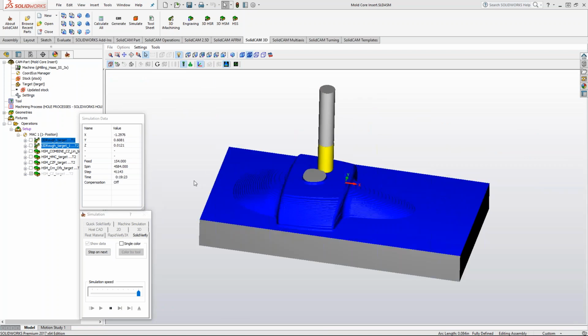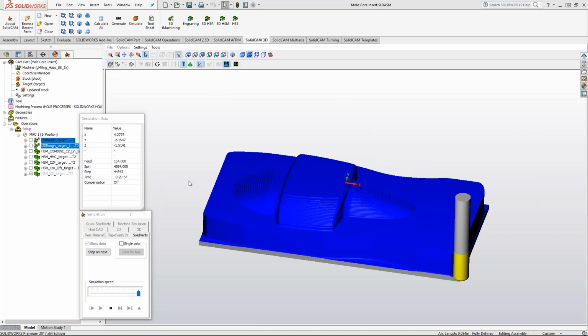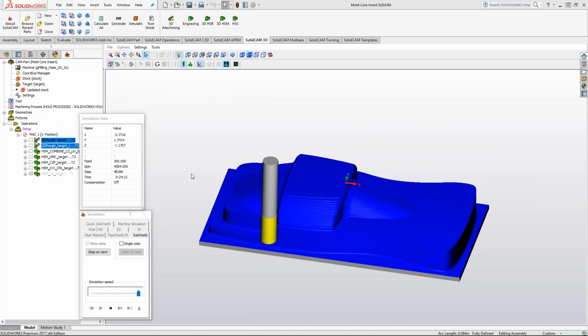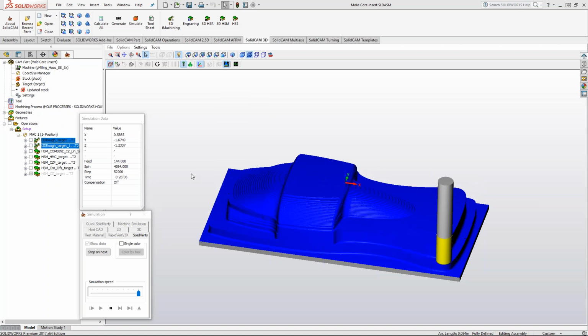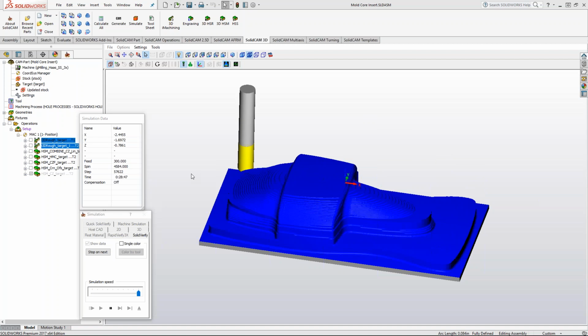I think this part was actually a clear part, so I had to have a much better finish on it. And again, this was P20 material. I think it was 28 to 30 Rockwell C. And that's what I ran most of the stuff that I did out of, was P20. It cuts good. It's pretty consistent as far as the finish goes, and it's easier to polish, and it's real shiny and pretty whenever you get through with it.